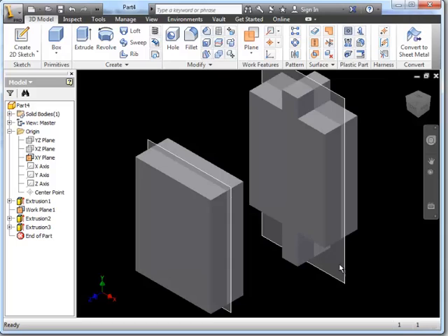So these are important things to understand: work planes and how to slice graphics. Now you can only slice graphics, you won't see the tool, unless you're in a sketch. And projecting geometry, of course, is also an important thing, and that only occurs when you're in a sketch.